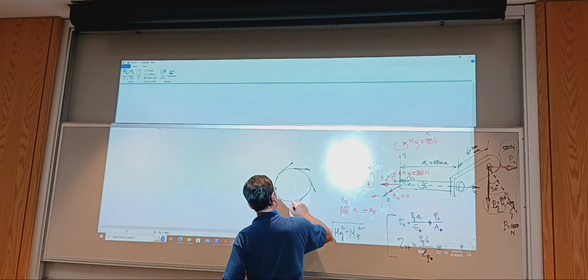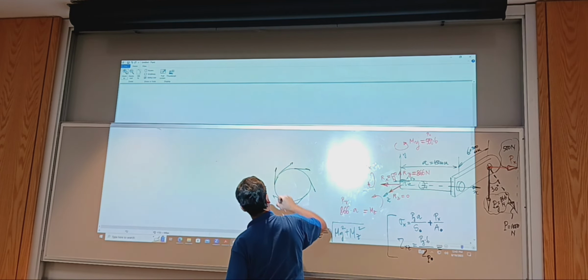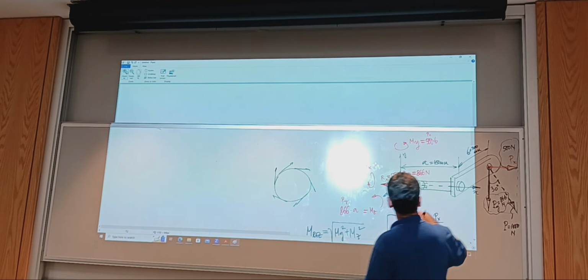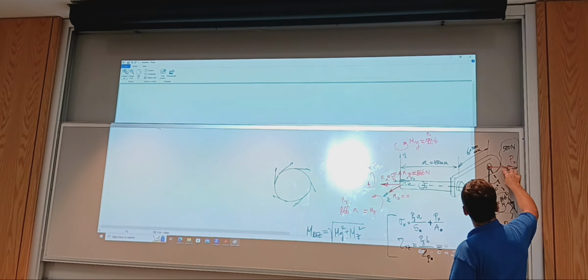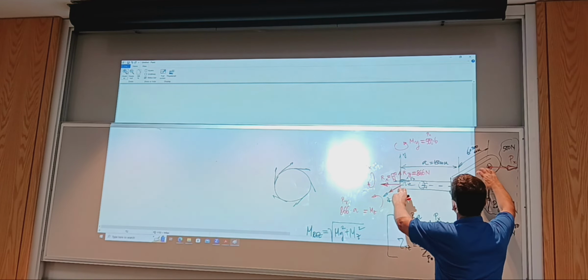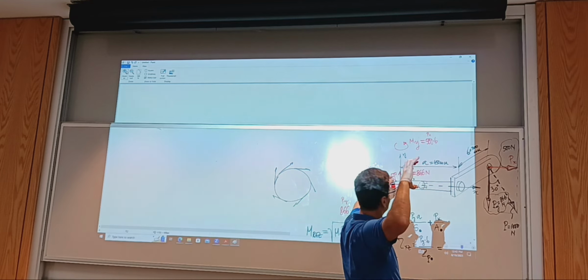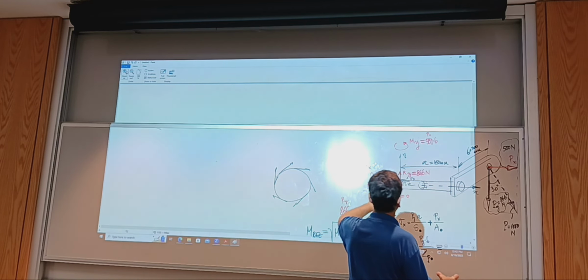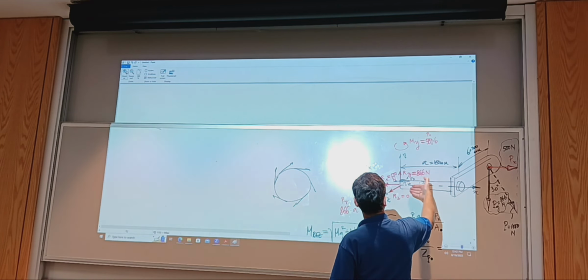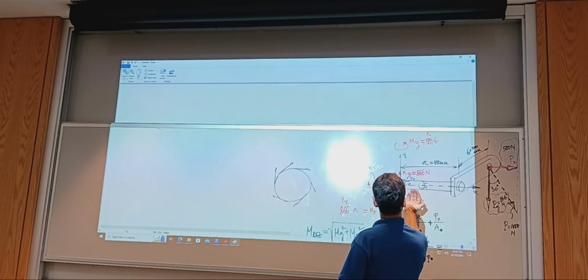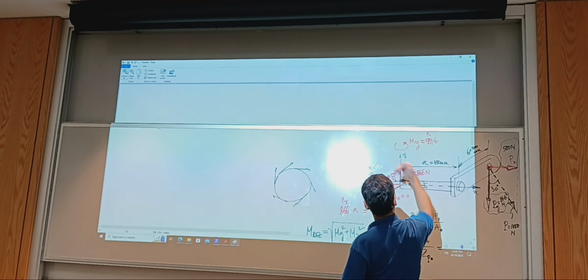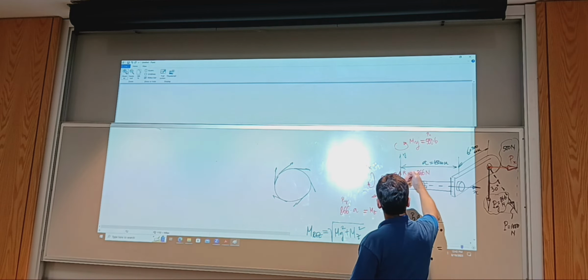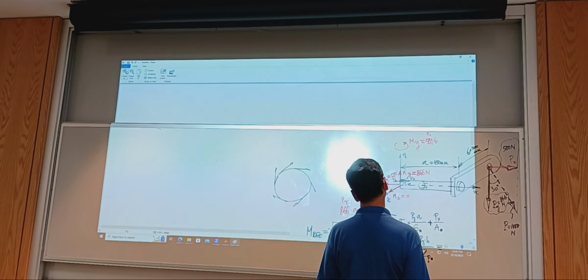The maximum will be somewhere in between. As you apply these forces together, one will tend to bend the part this way, the other one down. So maximum tensile stress will be somewhere behind at some angle, not on top, not horizontal, at some angle.